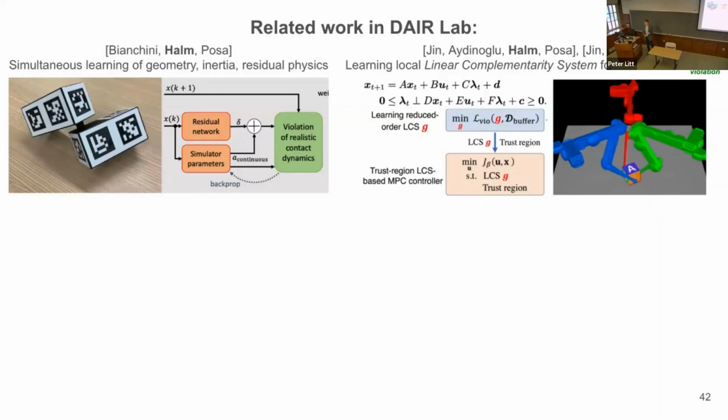And how you can input that into a model predictive controller to conduct effective manipulation of novel objects learned from very little data. And you can see a simulated example of his method here, reorienting and moving this cube with a three-fingered gripper in simulation.